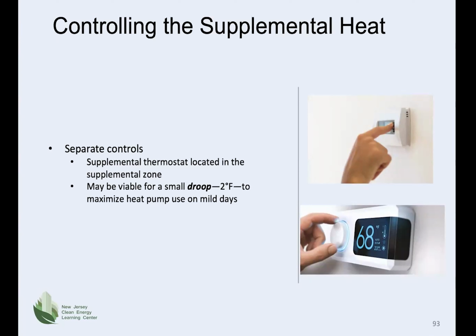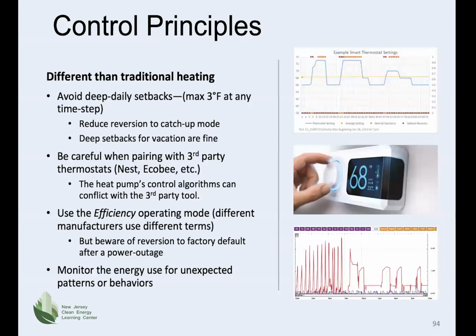Now, supplemental heat is a little different than backup heat, but they tend to use it here sometimes interchangeably. But backup heat is usually a legacy system where you have the ability to heat the entire home without the heat pump. And supplemental heat is usually when it's some form of heat added to the heat production of the heat pump. This is the way that you usually control supplemental heat. So these are some control principles.